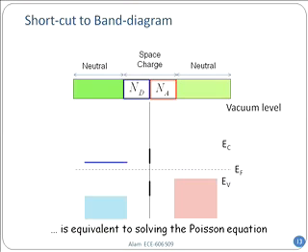The next thing I have to do, if I know what the material is, of course, let's say silicon, I know the band gap. So I will draw the valence band line. Okay, that's one side taken care of in the bulk region. What about the other side? I already know EF, I have drawn it on the piece of paper. And that's the chi1, that solid black line. That's the vacuum level. So I also have to draw the vacuum level first.